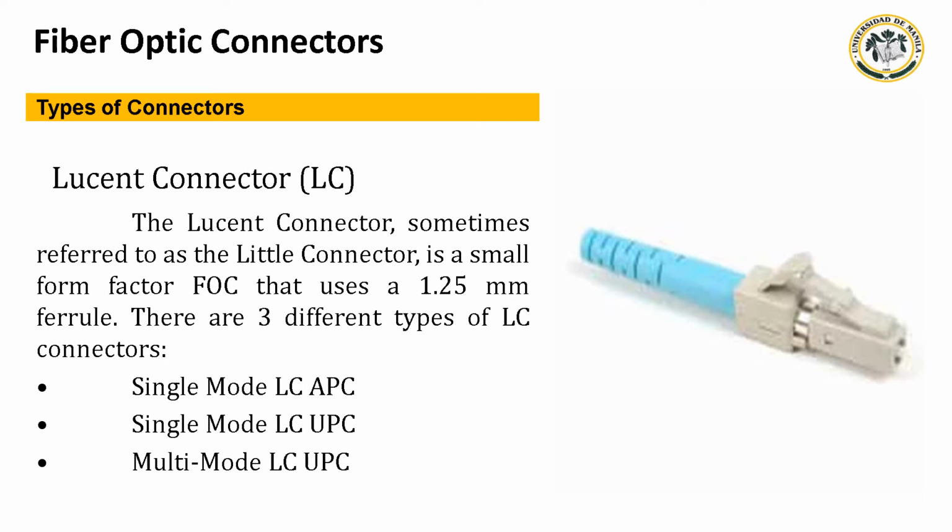Having half the footprint of the SC connector gives it huge popularity in datacoms and other high-density patch applications, as its combination of small size and latch feature make it ideal for densely populated rack panels. With the introduction of LC compatible transceivers and active networking components, its steady growth in this arena is likely to continue.